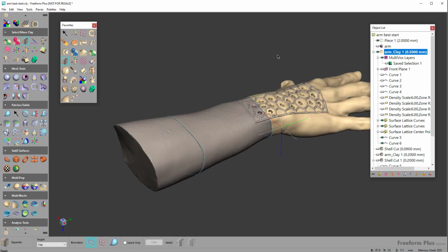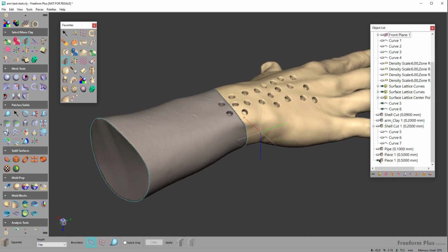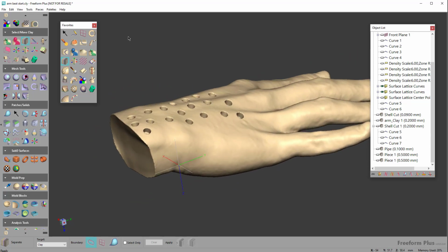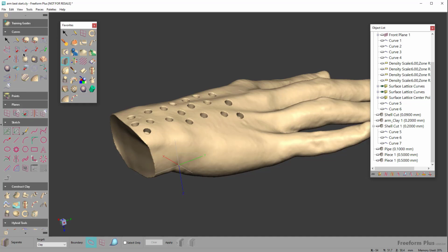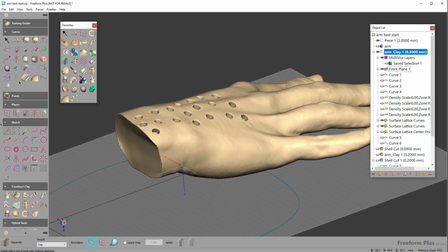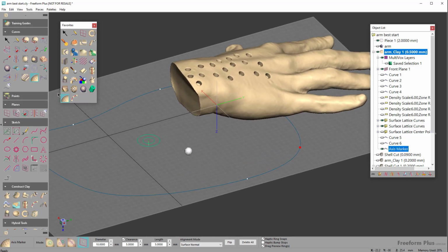And finally, the last one, there's lots of other enhancements, by the way. These are just ones that I'm highlighting that I just like to point out, is the axis marker enhancements. So we now allow you to snap axis markers to a plane. So if I turn on this sketch plane, come over to axis marker, select plane, and then that'll allow me to click on the plane and create axis markers wherever I want to here.